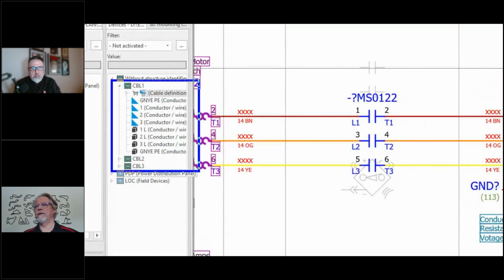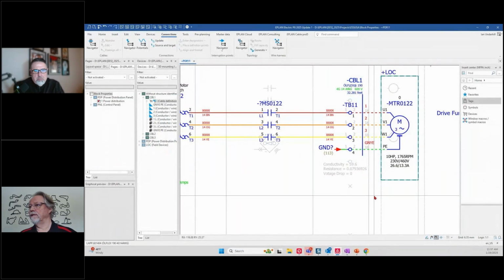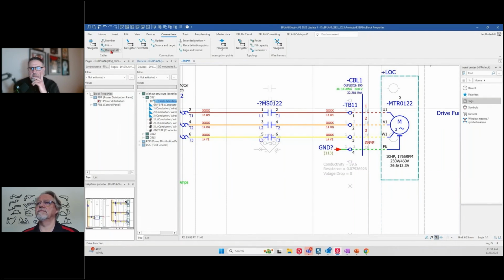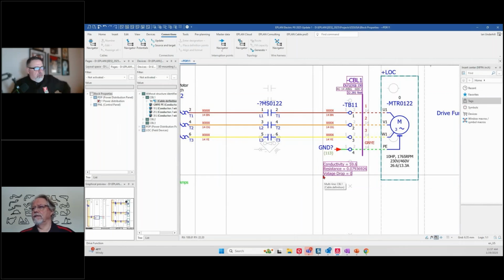You can see in my cable navigator, the links between the functions and the placement are broken. If I do an update, it can break those links. So just pay attention. In this case, I do a reassign all, and then I know that the value I got was good. So just pay attention: if you make changes, you do an update, update your connections and just check.